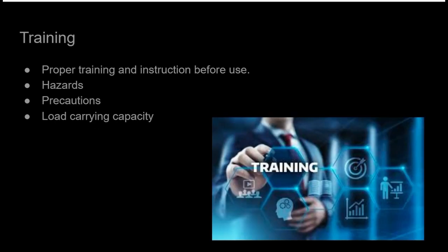Before using a scaffold, workers must be trained on the hazards of the work and the work area, precautions to take to prevent harm, and the load and load-carrying capacities of the scaffolds they will use. Workers who erect, dismantle, operate, inspect, or repair scaffolds need additional training on how to perform their duty safely.